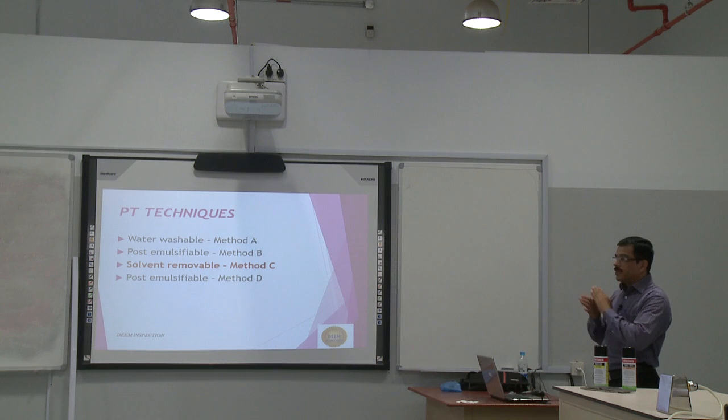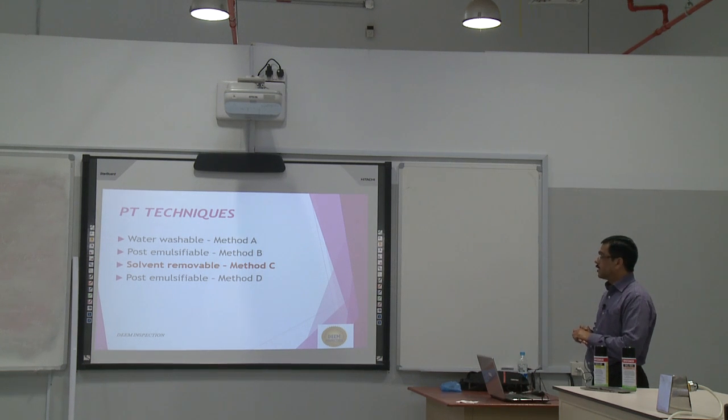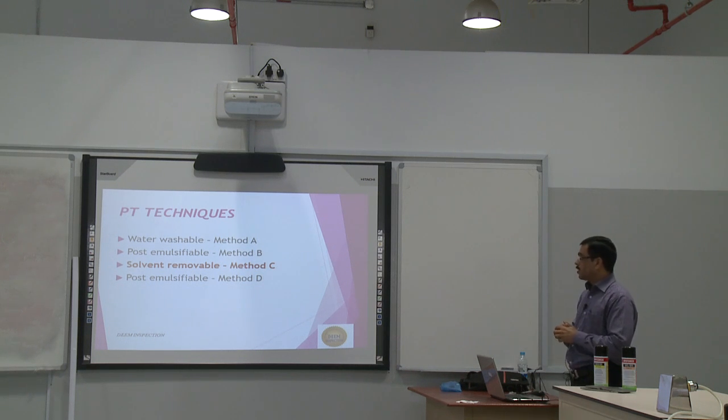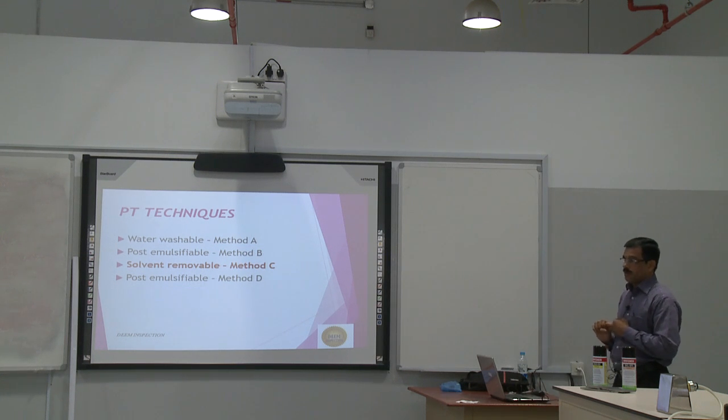These are the 4 methods we already discussed: water washable, post emulsifiable, solvent removable, and post emulsifiable method D also. How we decide the method depends on how the penetrant is removed. If it is removed by solvent, that is solvent removable. If it is removed by water, that is water washable, or the post emulsification method.